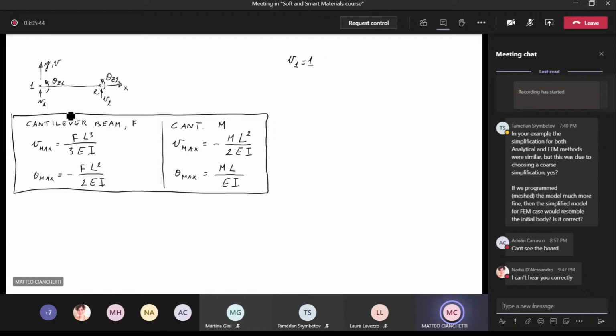The order of degrees of freedom is usually the degree of freedom on X, Y, Z, and then rotation about X, rotation about Y, rotation about Z. And this is node by node. If I'm able to do that at the end of this class, I will make an example of an entire matrix with all the ordered degrees of freedom. Okay?